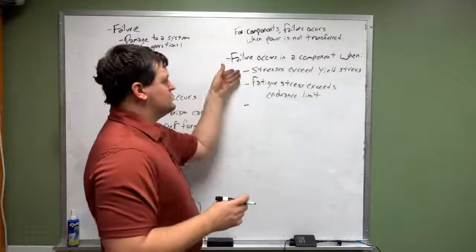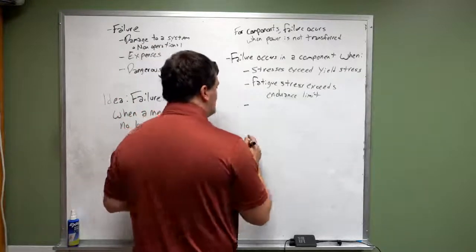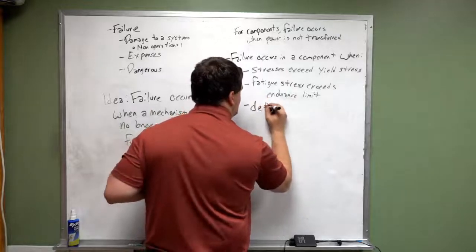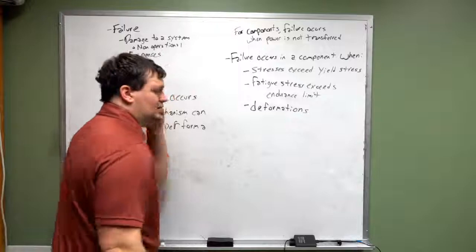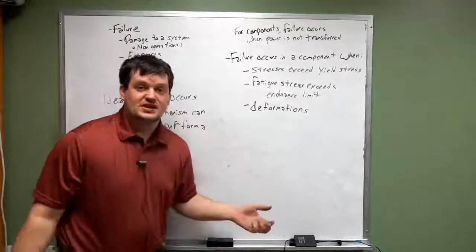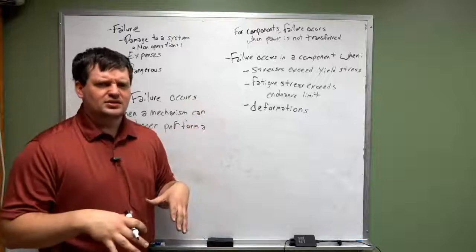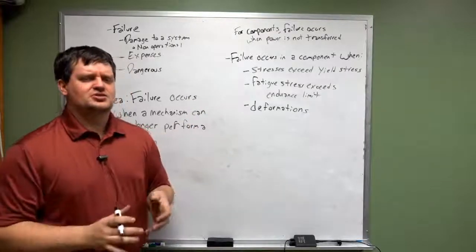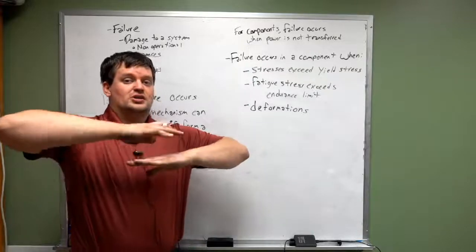Okay? So first of all, stresses. Second of all, fatigue. And then third of all, deformations. Okay? If you have excessive deformations in an axle, it can cause buckling, particularly if it's in a large amount of compression. It can cause components to skip.